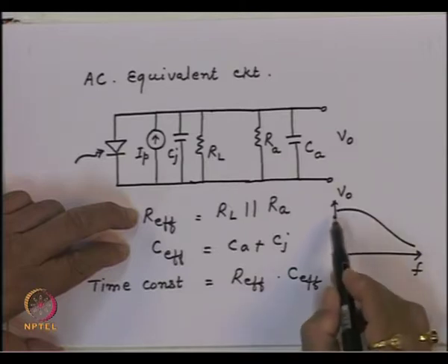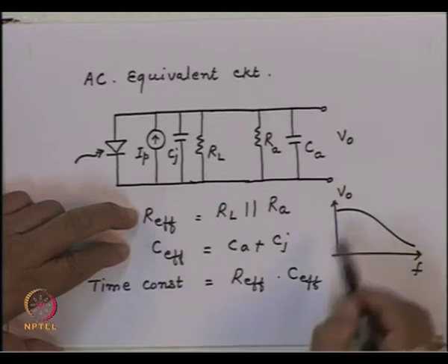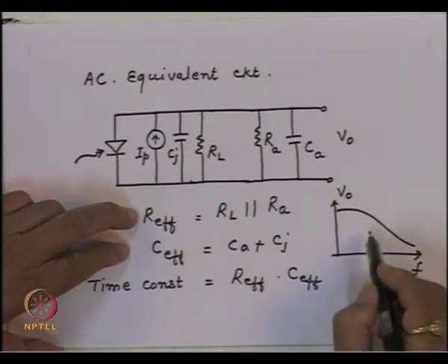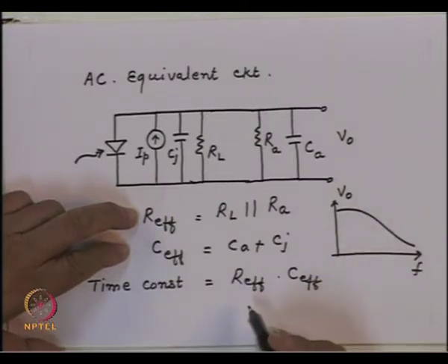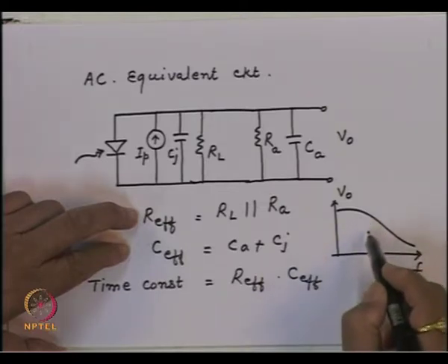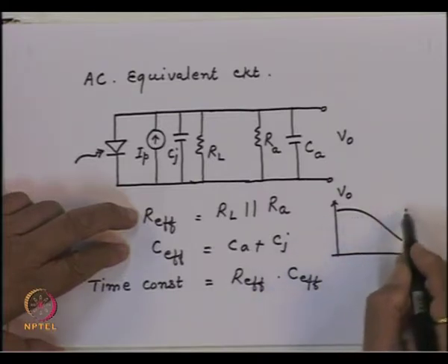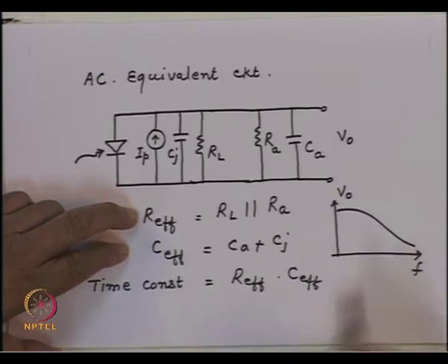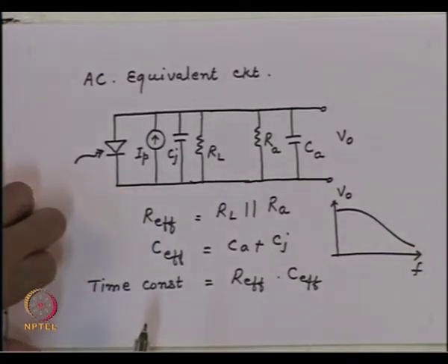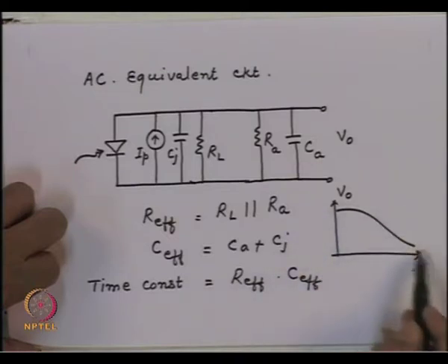So one of the requirements then is that the loss of response which we have at high frequency has to be restored. We have to provide an equivalent high frequency circuit, so that this frequency response becomes reasonably flat over a wide range of frequencies. That is a device called an equalizer, which has a frequency response which is more or less the opposite of this frequency response.